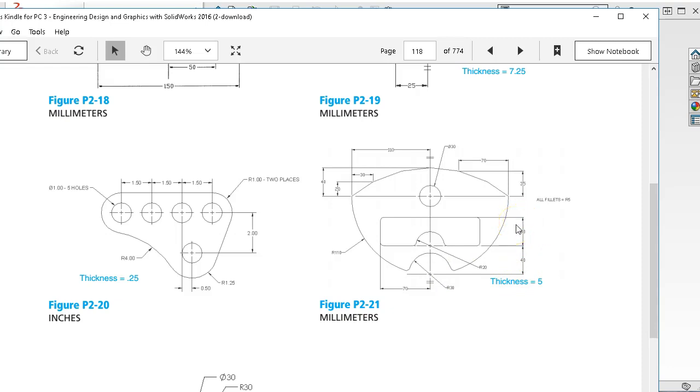So it's not explicitly called out, but based on the view and the direction, that's about what we have to go on. So if this was a working drawing, I would probably go ahead and put in a firm dimension that says, whatever, either what this gap is, or from the circle center to the center of this arc.